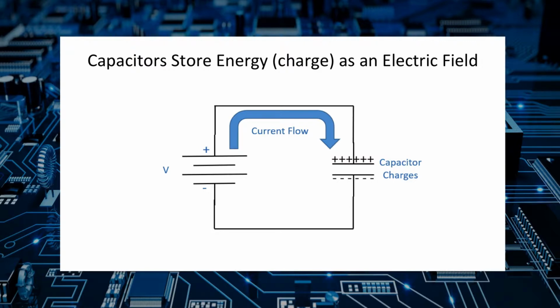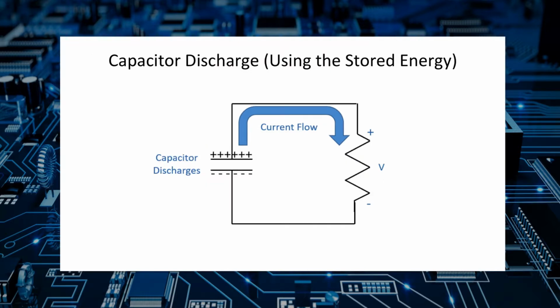If we apply a voltage across a capacitor circuit, the capacitor starts to charge and continues to charge until it reaches its final voltage. But how quickly does it charge? Or, given the opposite condition, where we put a charged capacitor into a circuit, how quickly does the capacitor discharge? The rate of charge or discharge for a capacitor is a function of the capacitance, which we always measure in farads, and the resistance or impedance of the charge-discharge path, which is always measured in ohms.